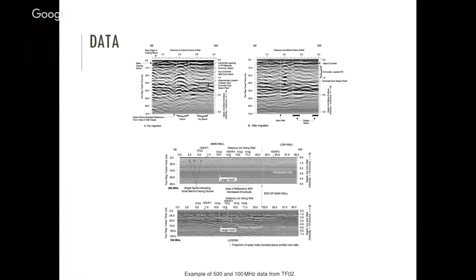The data that they got, as you can see here, they didn't have any real data diagrams provided from the DC resistivity, but they did provide the GPR ones. I can't read it here, but I believe right here they were able to identify a void. And in the paper, they also mentioned that in the top couple surfaces they found many areas with a lot of voids. Also, you can see down here there are larger voids as you go deeper into the wall.